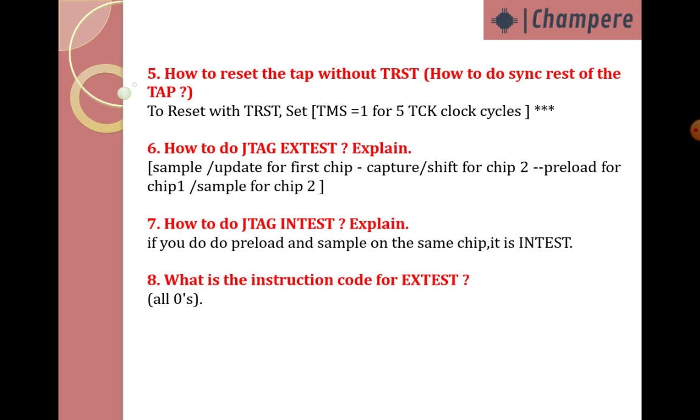Next, how to reset the TAP without TRST? TRST means test reset. How to do a synchronous reset of the TAP? To reset without TRST, we need to set TMS equal to 1 for 5 TCK clock cycles. So automatically, without test reset, the TAP will be reset.